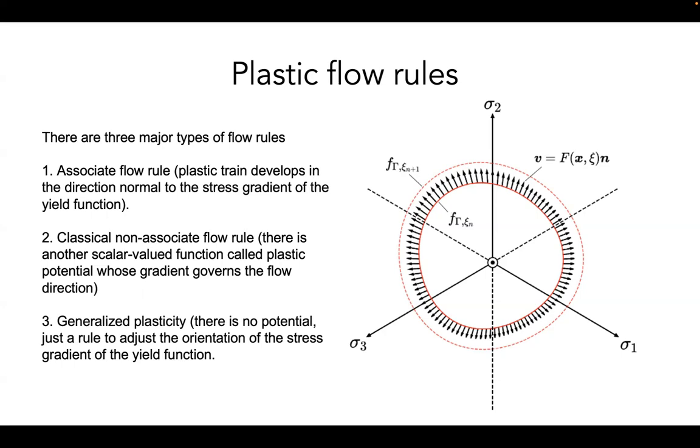Why is that? Because in this axis, I should have no component. All the arrows are shifting orthogonal to the hydrostatic axis. Orthogonal, geometrically orthogonal, means that they're independent of that, and what it translates to is that there would be no volumetric change. Because along this 111 line, sigma 1, sigma 2, sigma 3, I'm shifting straight. This is at 45 degrees, and I'm just going up along that, and along this normal direction I would have no volumetric component.